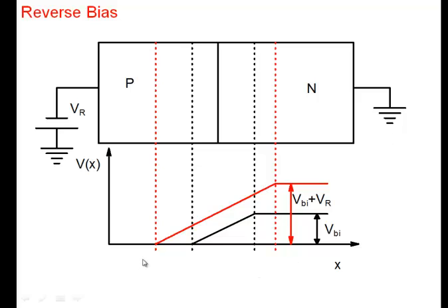And for example, I wanted to caution you that I've put these pictures here. It shows voltage changing like this here, right? Voltage changing from here to here like this here. This is a very simplified picture. The actual voltage that changes in the depletion region is not linear. It's not linear. It will change in a more complicated manner.